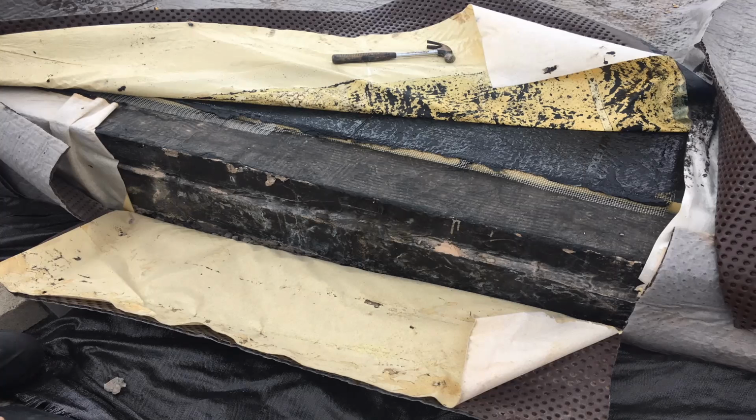And what happens is that rainwater falls on the deck, it gets onto the waterproofing system, it falls down, goes down the slot, forms basically a little river down there, and that gets into the structure, which is precast hollow core units with hollow pores, goes along the hollow pores, and it empties out like a waterfall. So those are the defects that led to that failure.